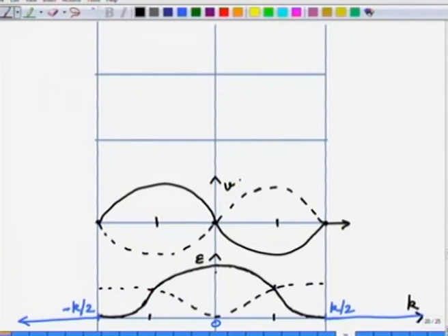Remember, velocity is defined for an electron if a site is occupied. If it is not occupied, obviously there is no question of velocity then, though there is a relationship called the slope of the E versus k curve. Though there is a slope of E versus k, the electron must be on that site to consider its velocity, to talk about its velocity anyways. All right, so that is the velocity.